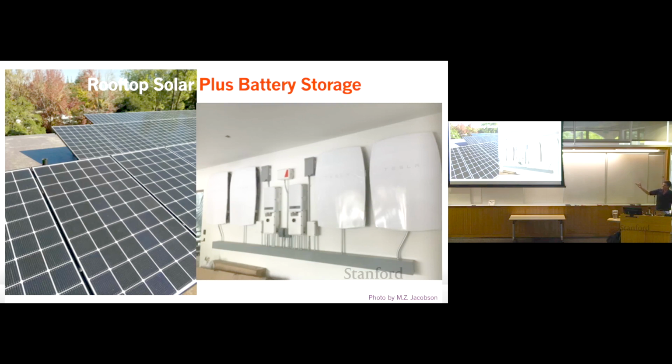The way they operate is, in the morning, the sun starts providing electricity through the panels. Household electricity is met with the solar directly. The excess goes to the batteries, so the batteries are filled starting in the morning. When the batteries are filled and no more electricity is needed for the home, the rest gets sent to the grid, and I basically sell the electricity to the grid. And then at night, when the sun goes down, the batteries kick in and provide electricity for the home.